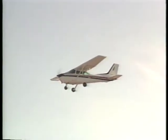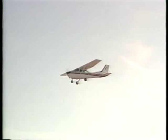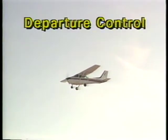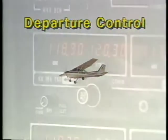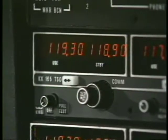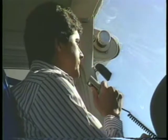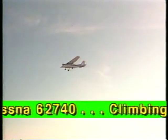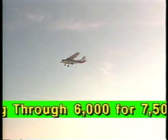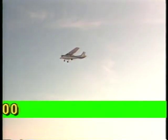Where radar is available, the controller may request that you contact departure control. Cessna 740, contact departure control. Because you are being handed off from the tower to departure control, the controller is expecting your transmission. Thus, your initial contact is very brief. Sudden departure, Cessna 62740, climbing through 6,000 for 7,500.